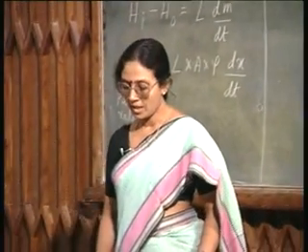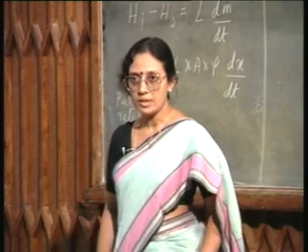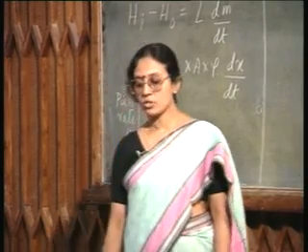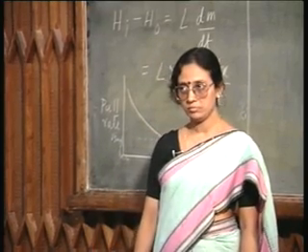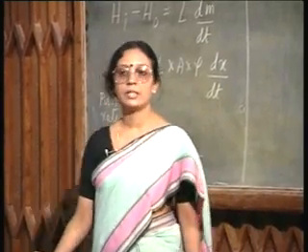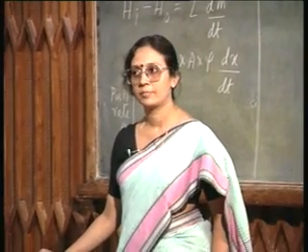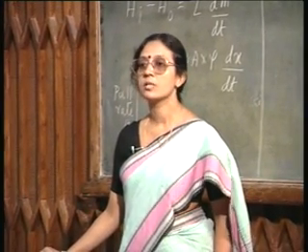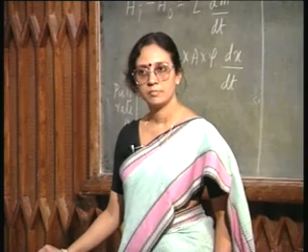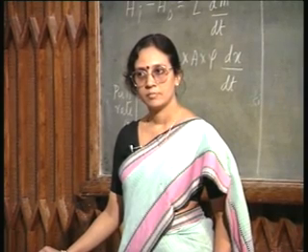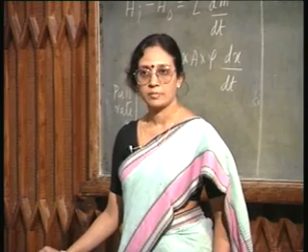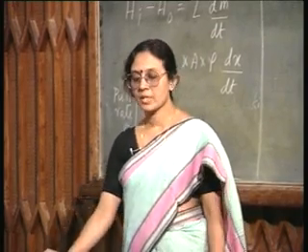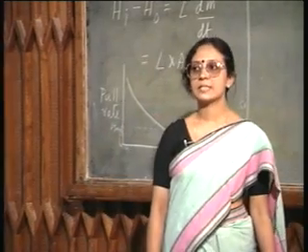You see, any impurity will have a solid solubility in the crystal and it will also have an equilibrium solubility in the melt, and these two are not necessarily the same. It has a different solubility in the crystal and in the melt.